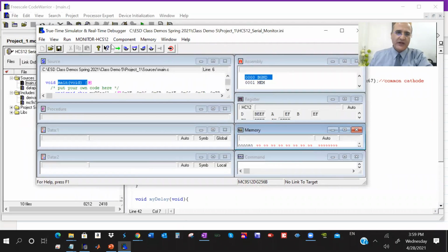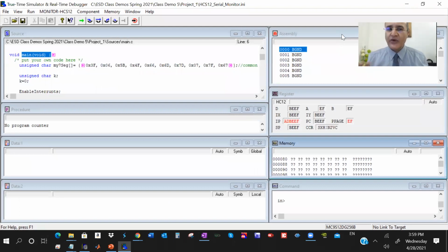The setting here configures the PLL clock and changes accordingly the bus clock, and thus how fast instructions can run. But when we run the code directly from the flash memory, the code configuring the PLL clock is not there. We didn't write it, so it ran much slower. That is the reason.